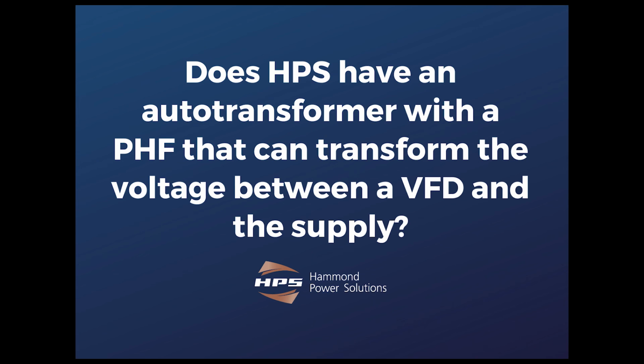Yeah, just to build on that, Mike, as Mike said, we've got standard harmonic filters available for 480 volts and 600 volts at 60 hertz. But if there's a special need out there, if you come across a different system voltage in that 600 volts and below range, we can definitely look at it and design special filters.